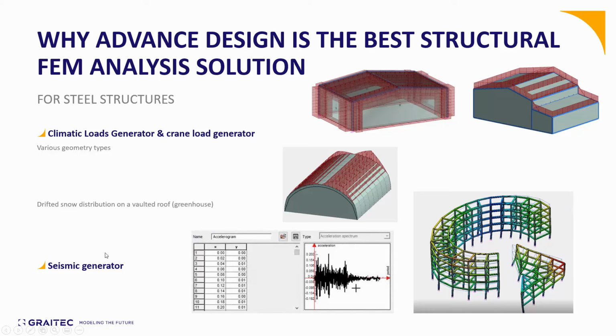will take care of your load generation. Same thing for the seismic load generator. We have several tools in case you want to evaluate the structure for seismic loads. We have modal analysis, we have the RSA method, we have spectral analysis, and we also have time history analysis, as you see here. So there's no limitation on applying forces to your structure.